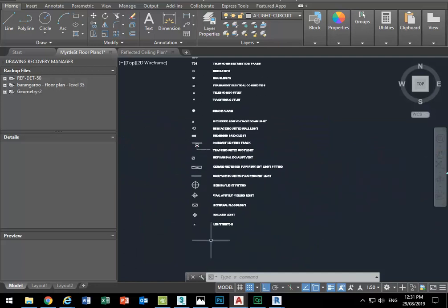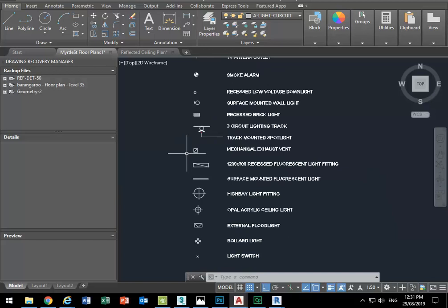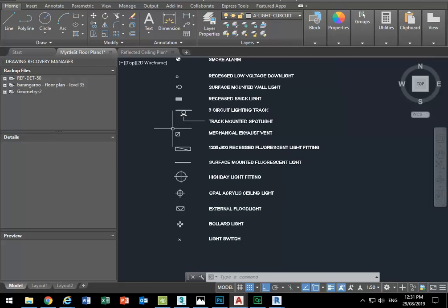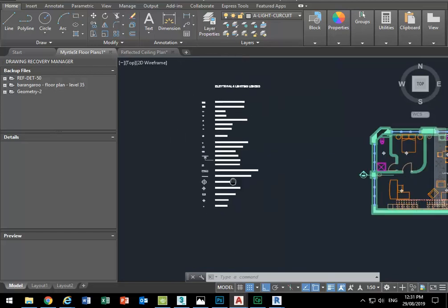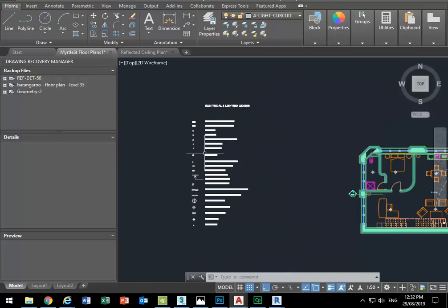Okay, so do you know what ducts look like? There isn't a symbol here, I don't think. Oh, yeah, here we go. There's an exhaust vent. So, okay, again, it gets a bit complicated. There are different approaches, but you can have a two-way system where you have supply air and return air, and that's the best. And with those, you generally need more supply outlets than return air.